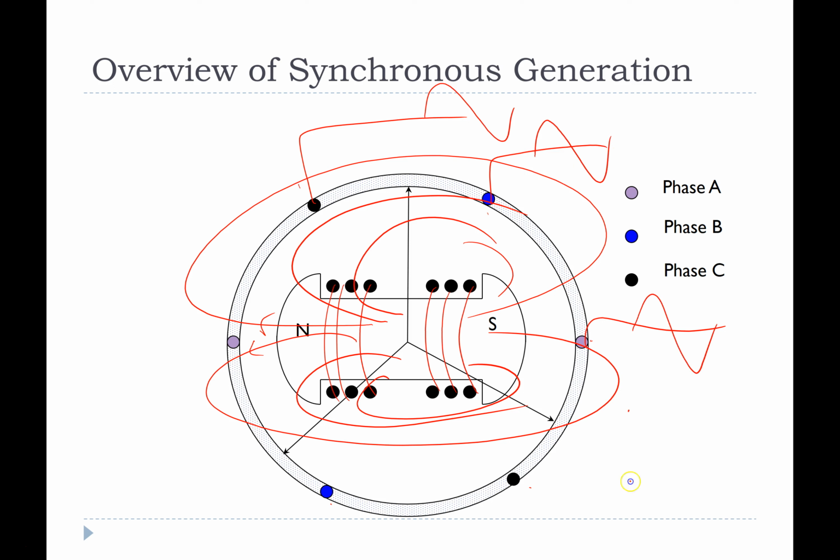then it cuts the conductors and it induces an EMF in each one. And if we look at the three of them together, we will see that these are the three-phase powers. So the three-phase voltages that we get, they're all shifted by 120 degrees apart because the magnet cuts them 120 degrees apart. They're separated through 120 degrees. So the North Pole will pass here 120 degrees after it passes the next one or the previous one.